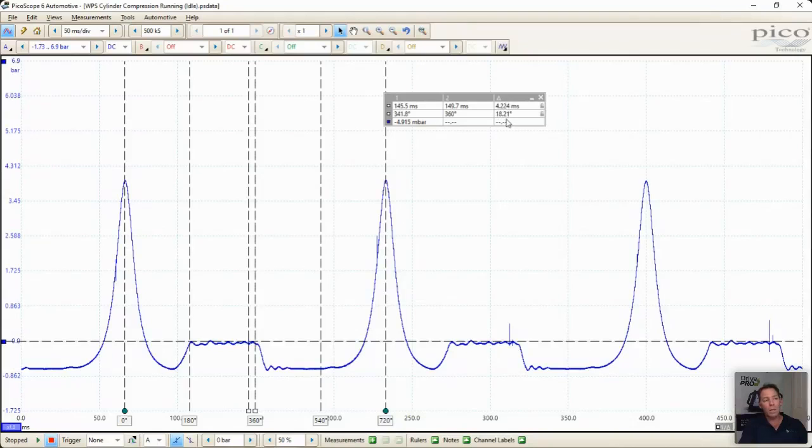And in this case here, that's 18. If this is supposed to be 25 degrees, I can definitively tell you that the cam belt stretched or the cam chain stretched. And that's using the vertical rulers and my rotational rulers together. So that's probably a little bit more complex measurement, but it's a very, very good one to use.